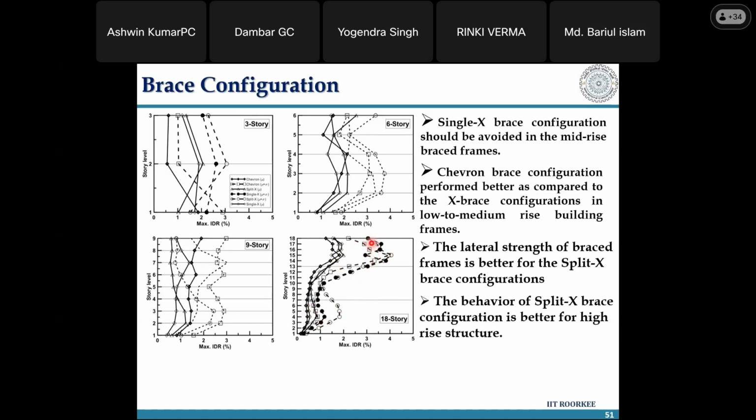The demand to capacity ratio has to be controlled so that it doesn't happen from one floor itself. But you can understand that at this particular location and at this location, let's say story number 3 to 7 and then 12 to 16 to 17, you will get yielding and buckling of the braces, with intermediate level braces not even performing anything. So to design your beams and columns, the local analysis and global analysis is to take the worst case scenario.